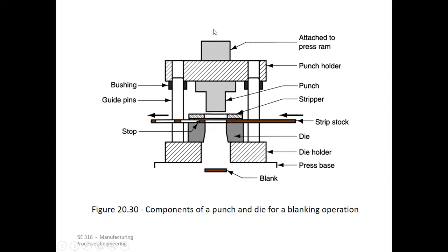That hydraulic energy is received from this ram and is transferred to this punch holder and therefore to the punch ultimately. So that energy is being transferred here, and then this punch holder, as the name suggests, will hold the punch. You have a punch here, and this punch holder has to slide down for the punch to move up and down. So how does this punch holder slide up and down?